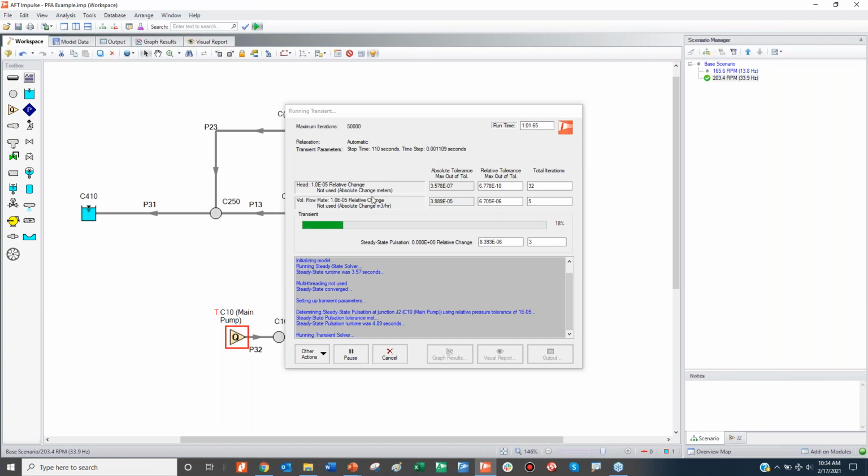So you can see how easily you can check for different vibration excitations to check whether or not your pump can operate. And if it does operate at that range, how close it would be to not complying with API 674. I'm going to end this because it would take too long to generate the results.